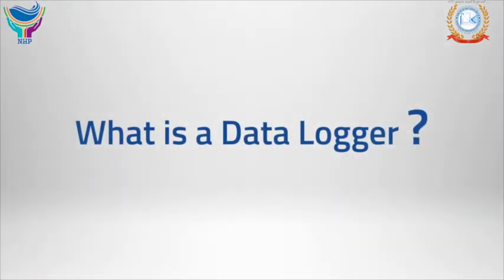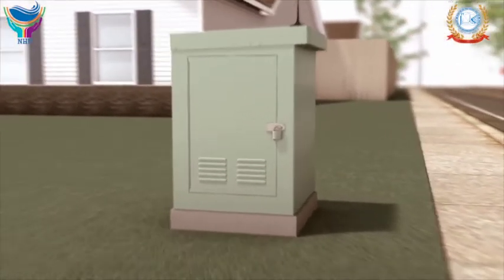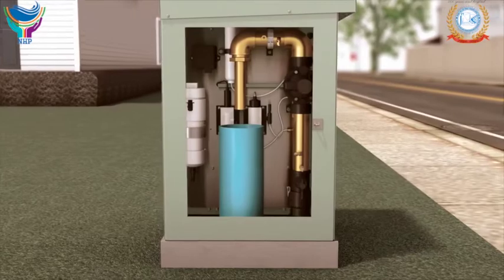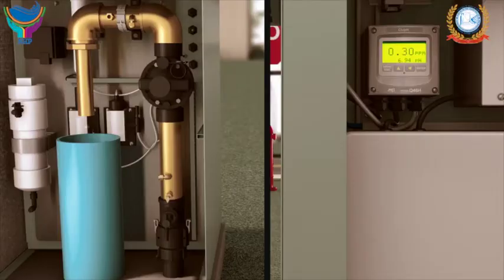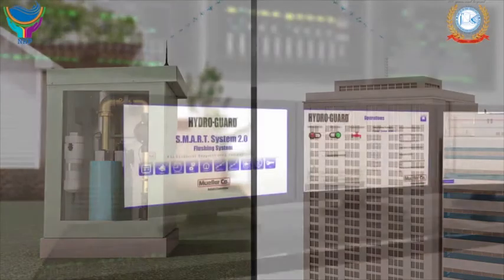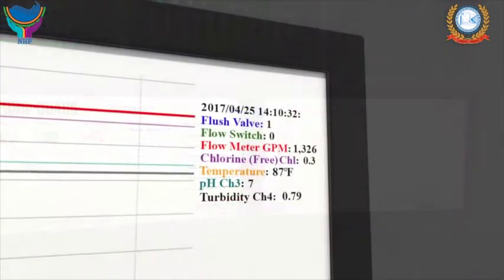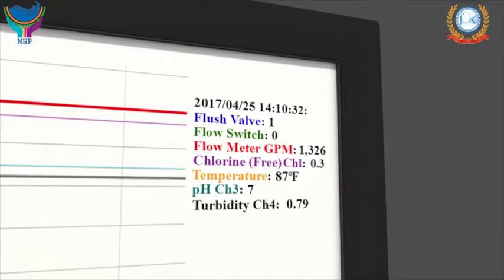So what is a data logger? The data logger is the heart of any hydrometeorological monitoring system. It performs various functions in the system, which includes sampling, acquiring the data at specified intervals, storing the data, maintaining the system time, providing the trigger for data collection and transmission, providing power supply to the sensors, providing the data to the transmitter, and responding to the user's queries either through telemetry or on-site.